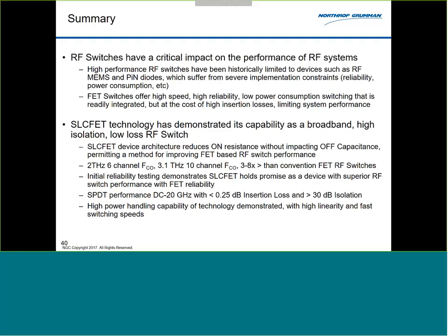We are looking at geometries and device architectures where we can increase that breakdown voltage to 120 volts or so. I've also had ideas, since I used to do the power device world, of translating the structure into more of a power device where we can increase that to 600 volts, 1200 volts. But there's not an enormous amount of interest at Northrop Grumman in some of those. We'll see if I'm ever successful in getting any of those architectures off the ground.